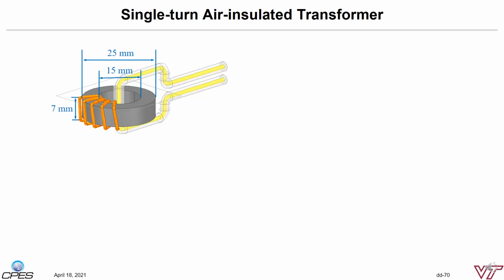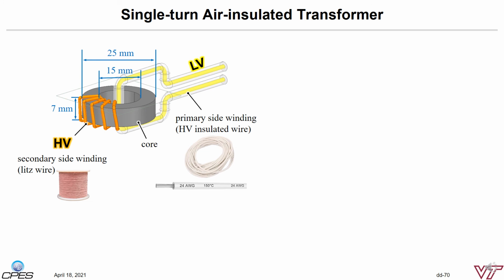The most critical design is the insulation around the megahertz small size transformer. A 3D FEA simulation model is shown in this page. The transformer is wound by the receiving side wire, which is on the high voltage side. The primary wire runs through the transformer.